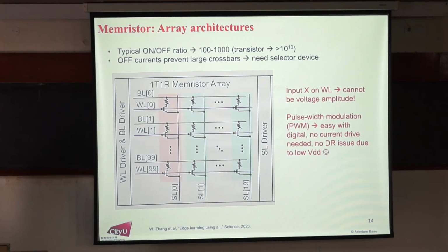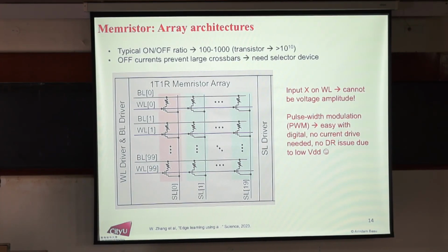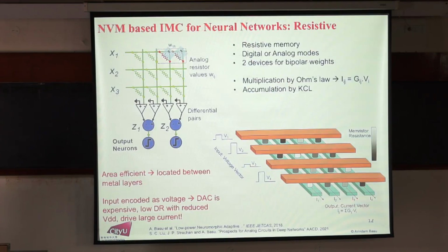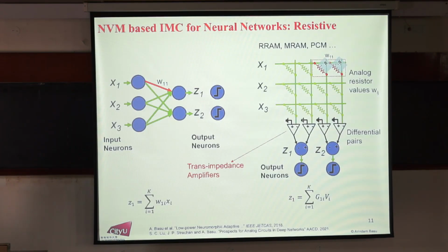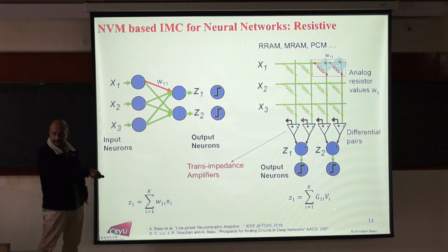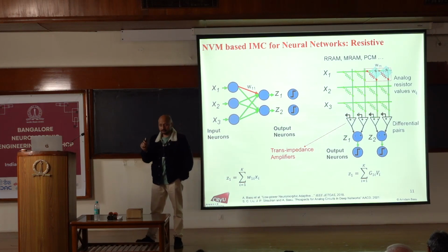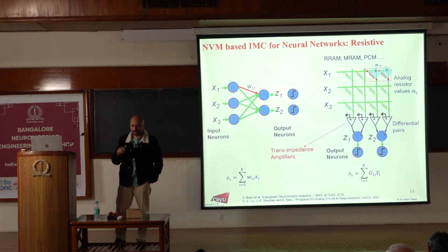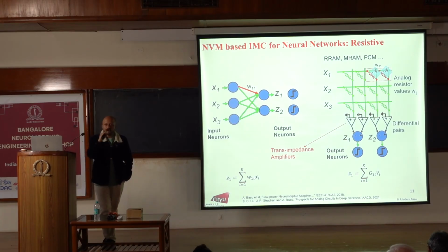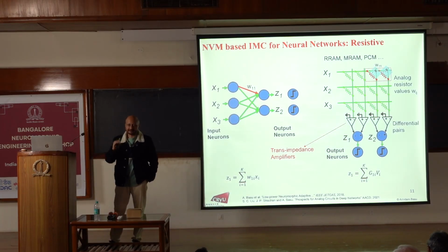Previously we had only the conductance, here you had G times V, where the input was encoded in V_i. In the pulse width case, what you have is V_DD times delta T_i. So basically the time that the signal is on is going to encode your input. The MOSFET is just on and off, so it's not in an intermediate state. Only the on resistance will play some role.